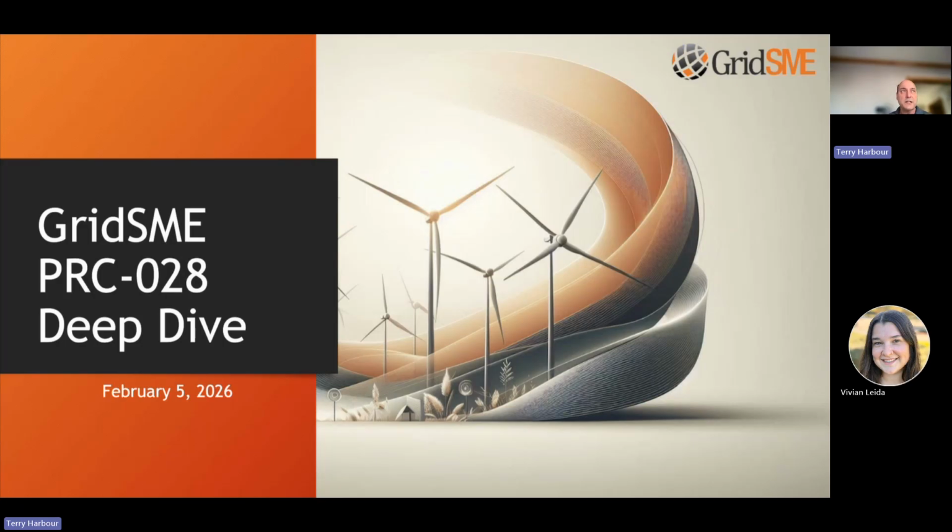So make sure that you're checking on their capabilities or with the manufacturers that you can indeed capture that 2-second record length. Another problem area might be gathering and time synchronizing all of the individual inverter data. There's a lot of data out there to capture and gather, and you've got to time synchronize it and make sure that you can put data out in the right format. So that might be another common bottleneck that we've seen so far.